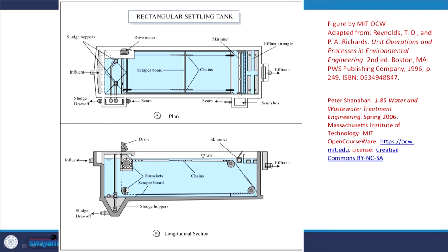So rectangular tank, narrow rectangular tanks anyway, as you can see here, this is the plan top view and this is the side view, let's say, right? Again, narrow rectangular sedimentation tanks are typically much better with respect to removal efficiency, let's say, right? But the issue here is that if you have long, narrow tanks, the area beside it you can't really use, right? So it's typically uneconomical for the plant with respect to the construction efficiency, even though the removal efficiency might be high. So that's one thing to keep in mind.